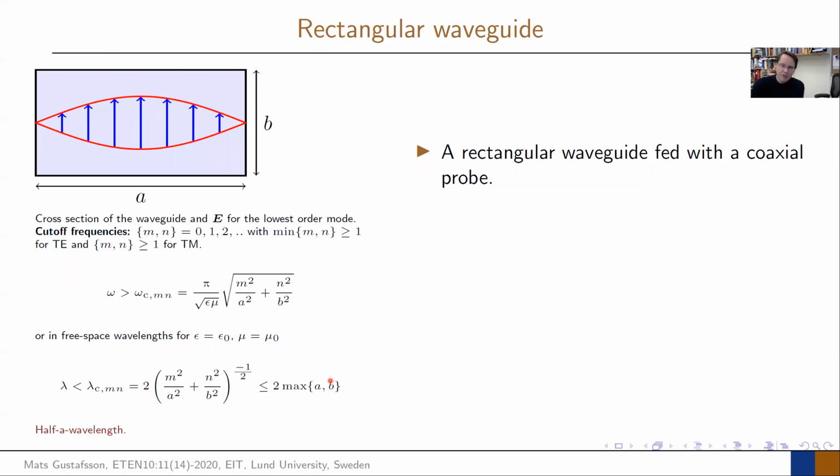I mentioned the solution to this. What can be seen in these cases is that the wavelength needed to get a propagating wave comes from the solution to Maxwell's equations inside of this structure. To get this solution, which is the lowest order mode, the angular frequency has to be over the cutoff frequency for the lowest order mode.